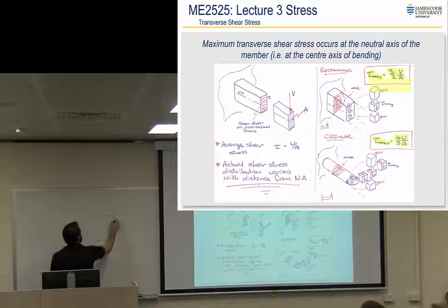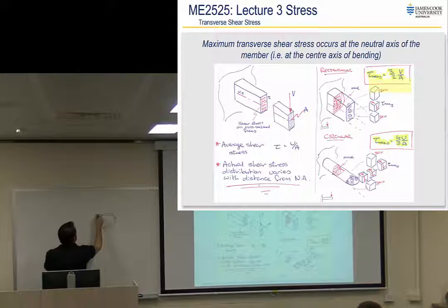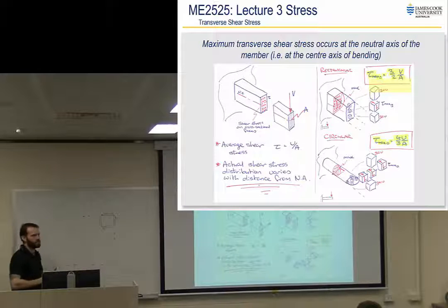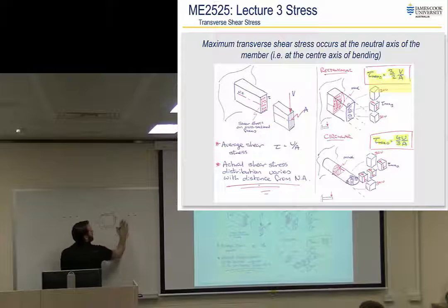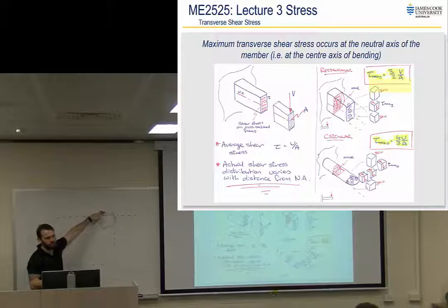We know that a shear element, if I have, let's say, shear on this element like so, that's the sort of front face. Now, I've got material over here actually applying that shear stress to the front face. Is there anything on the top edge of that beam to apply shear stress or shear force? There's nothing. And so if I've got nothing to apply shear stress at the top face, that means this top face of shear has to be 0.